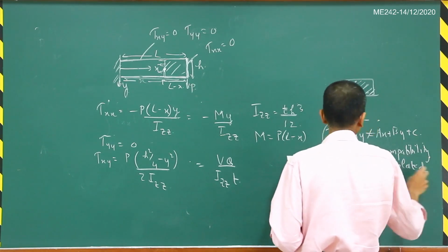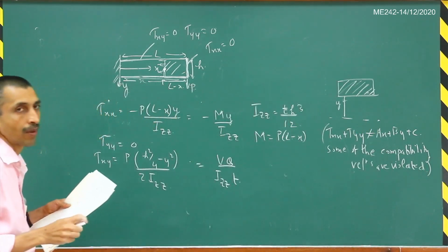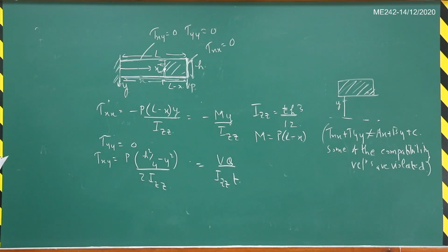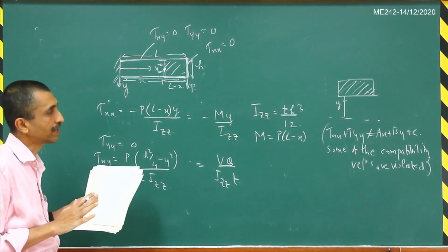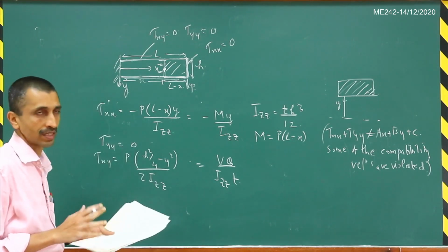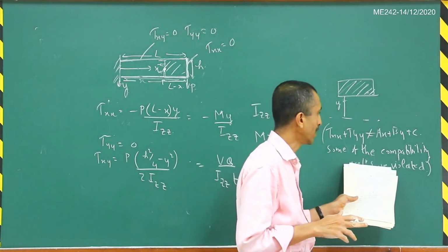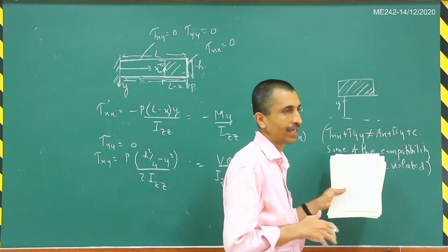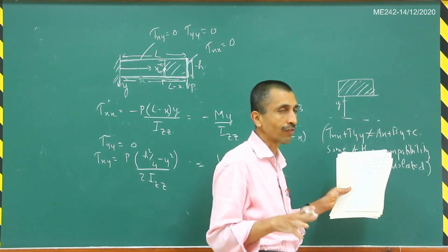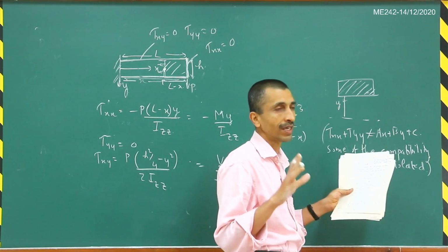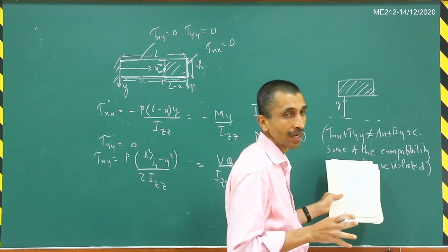So that is fine. As we discussed, the plane stress is also an approximation, right? And so this is also fine. So within the context of the plane stress approximation, this is an exact solution. But here we'll see that the out of plane compatibility relation... the in plane compatibility relation is of course satisfied, because that is what we used to get the equation that del raised to 4 equal to 0. But the out of plane compatibility relations, some of them are going to be violated.